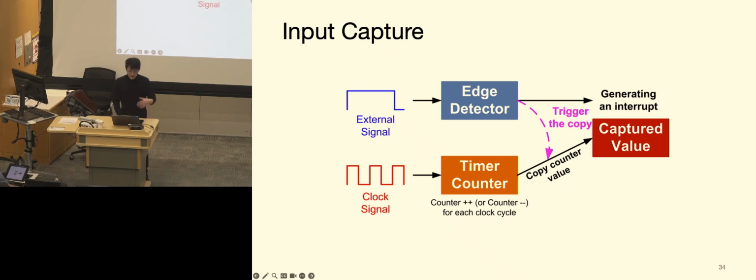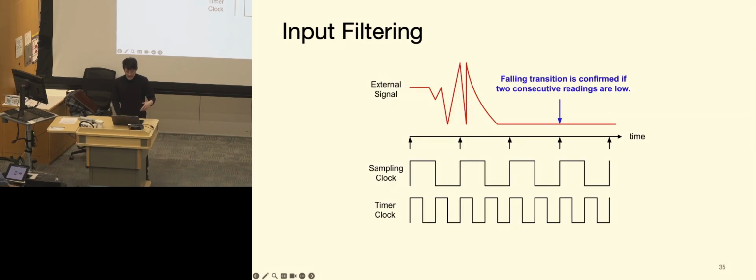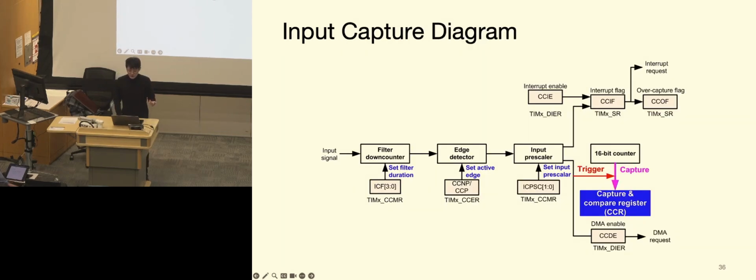The signal could very much look like this. At the hardware level, they do have an additional counter filter. It just keeps track and makes sure this state or this edge happened for some amount of time, and only then records it. This is the pre-filtering, or filtering on the hardware level.